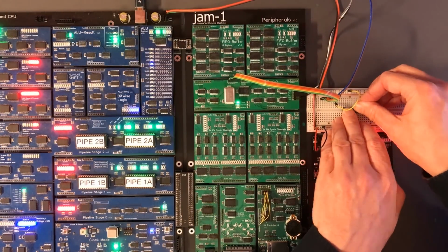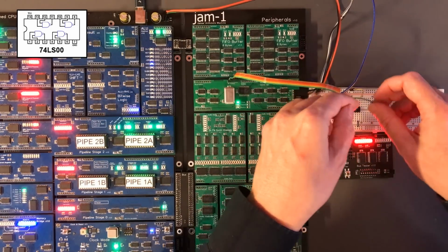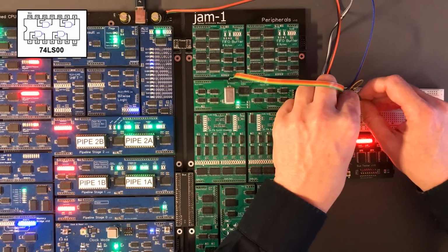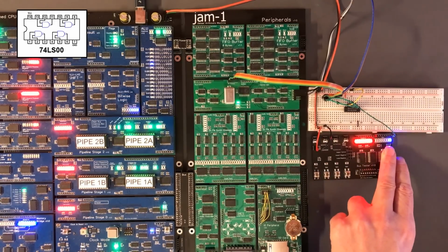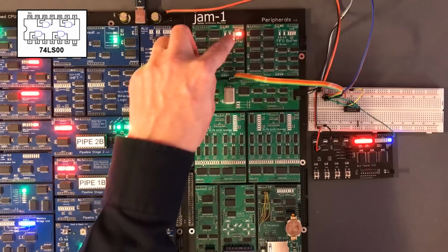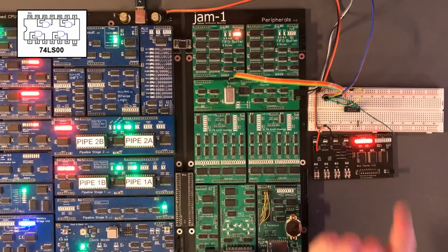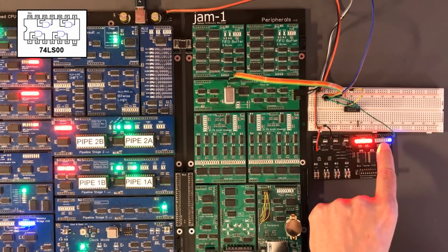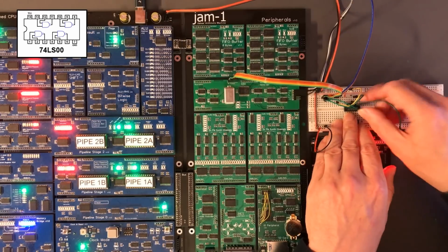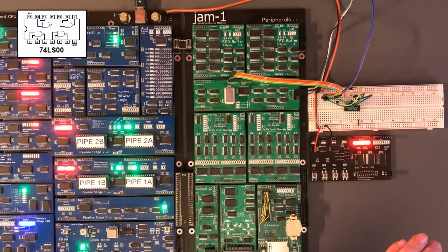Okay, so this is a NAND gate. Give it power and ground. I'm going to take bits 2 and 3 to 2 of the gate's inputs. So this is going to produce the opposite of the AND effect we want. So now we've got 5 and then we move on to 6. I expect the LED to extinguish, which it did. No real surprise there. And we want the inverted form of that. So by tying the inputs together, we can use the additional spare NAND gate as an inverter.